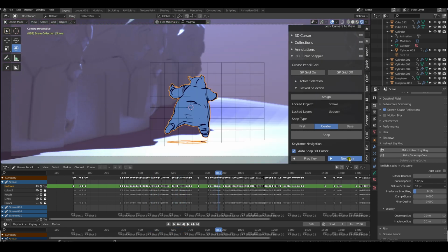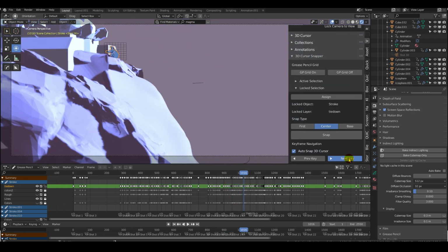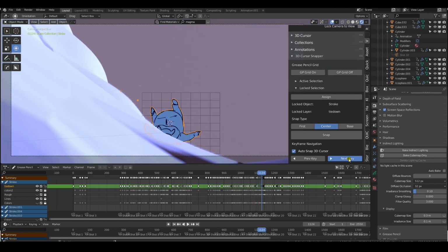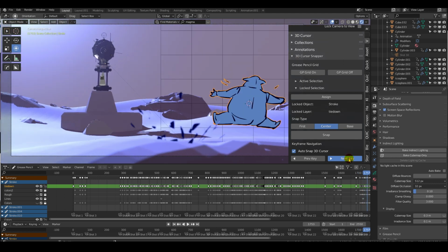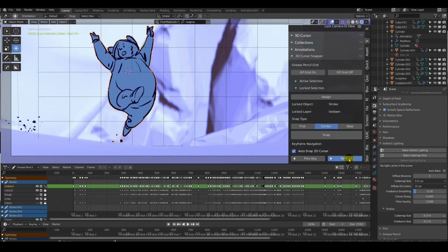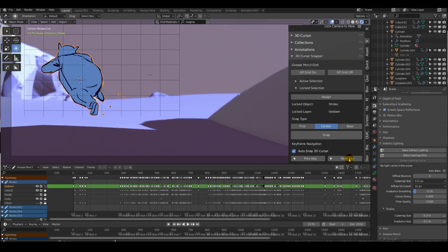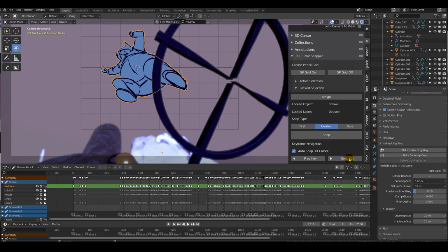The function of the add-on is actually very simple, but what it does allows us to unlock a massive amount of potential in the cursor method of placing our grease pencil drawing. Because the 3D cursor doesn't actually require any object keyframes for the grease pencil, it enables a very freeform kind of way of working wherein you place the cursor, you draw, you place the cursor, you draw wherever you want it in 3D space. So you can really feel out a pathway through an environment.